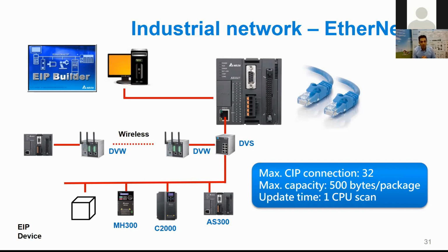Okay, we have a question. Is the power module mandatory for the AS series or optional? Thank you for the question. I forgot to mention: no, it is not mandatory. It is 24 volt only, so you can use your own power supply. But in addition, we also have our own power supply like the AS PS02. It is simply a power supply. So no, it is not mandatory. You can also supply it with your own 24 volt DC in your cabinet. Thank you for the question.